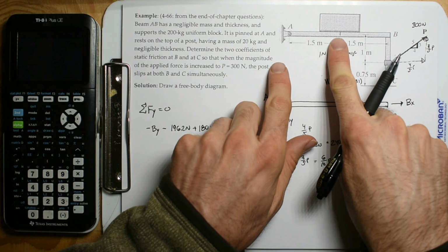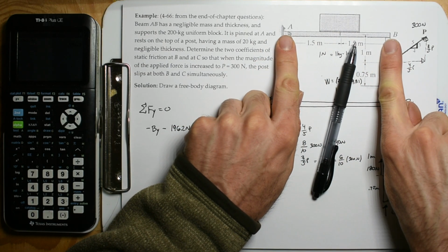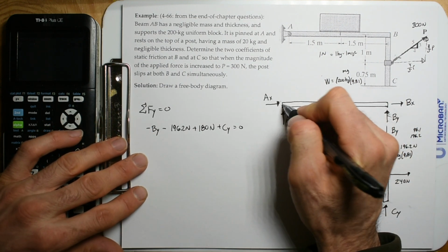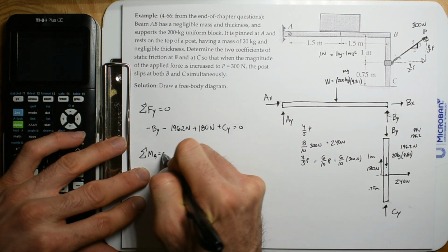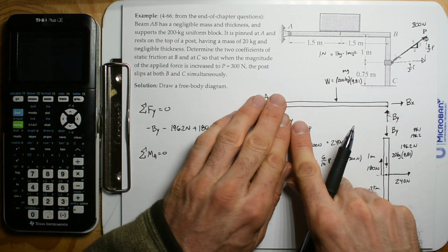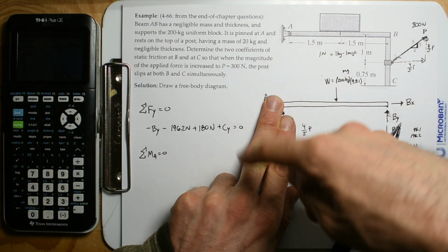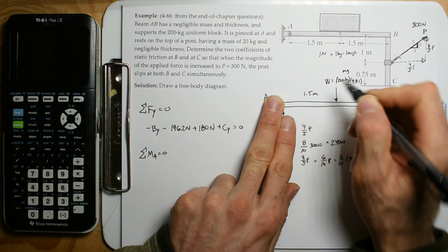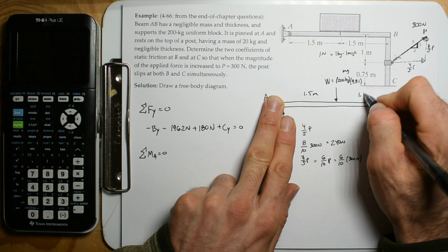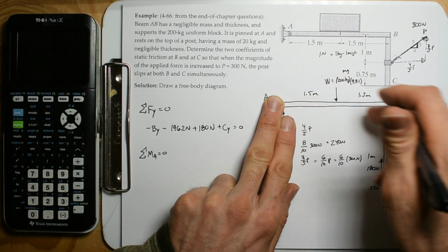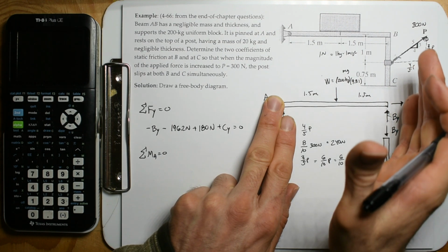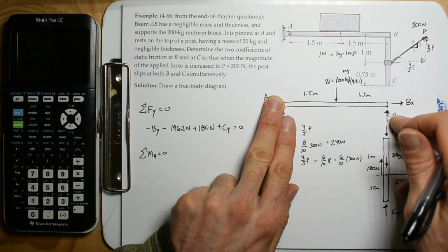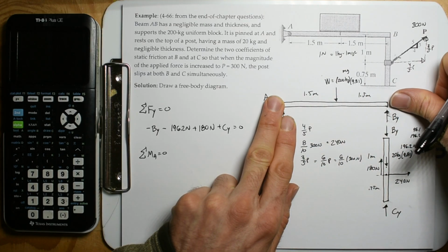But what we're going to have is this mass is evenly supported between 2 points. So that should just scream that this is going to be half. But we'll do it correctly. We're going to sum the moments about A, which is going to be 0. And if we do that, these forces go through A, so they're not part of generating a moment about A. This is the force that generates a moment. It's a distance of 1.5 meters. This force, BY, is twice the distance. So keep that in mind. Twice the distance means it's going to have twice the leverage, so it only needs to be half as potent. And BX goes through A. That doesn't generate a moment.